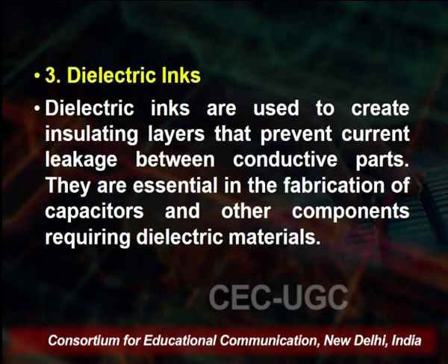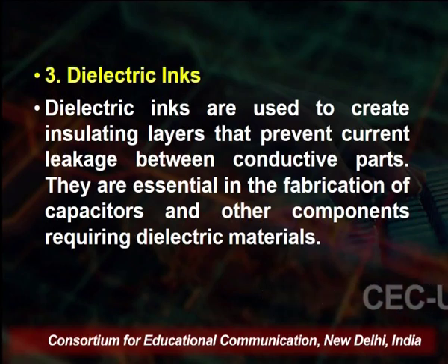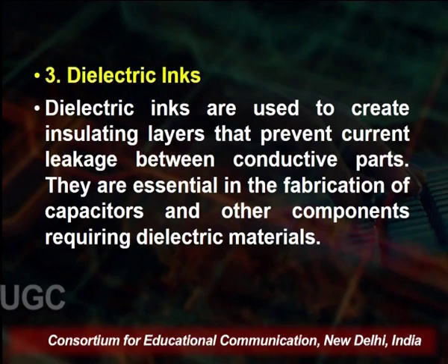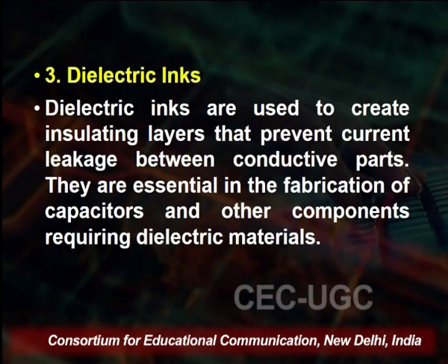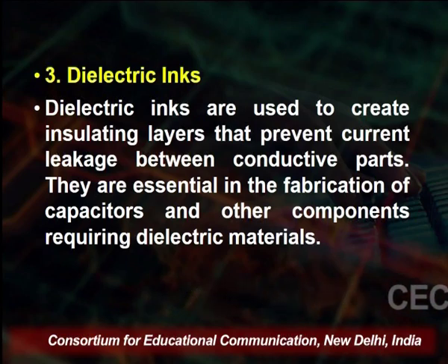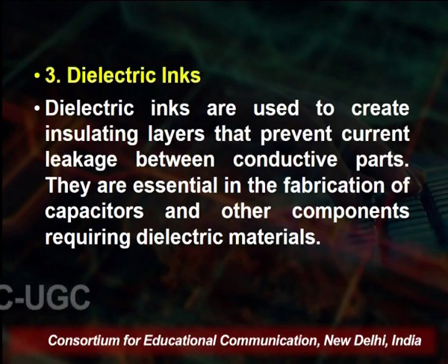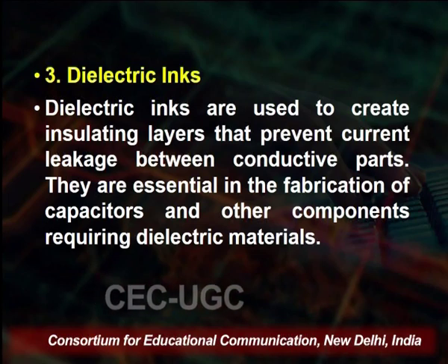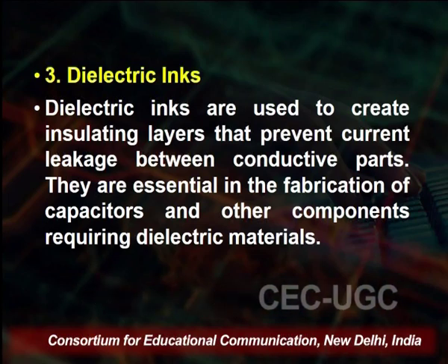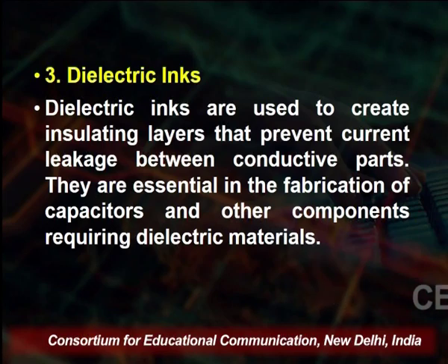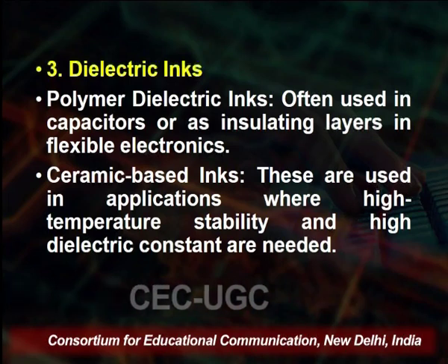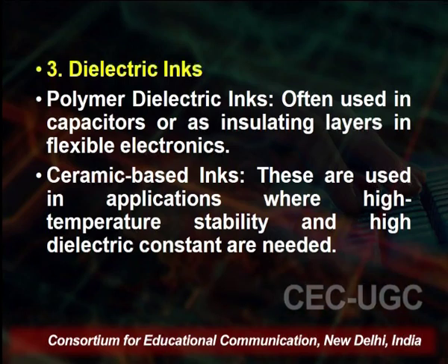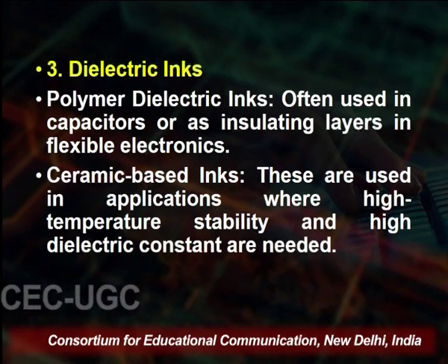Now, dielectric inks are used to create the insulating layer that prevents the current leakage. Means we prepare an insulating layer that prevents the current leakage between the conductive parts, and they are essential in the fabrication of capacitors and other components requiring the dielectric materials. Polymer dielectric ink, we can use; ceramic based ink we are having, which is often used for capacitors or insulating layers in the flexible electronics.